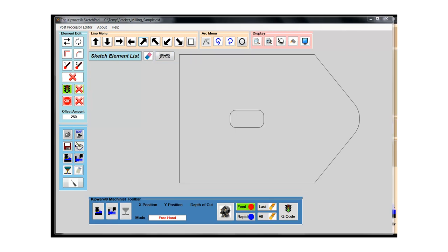So we're going to dive right into the drawing, and before I can do it, I need to do some calculations so that I can figure out a start point here where I can draw my tool path. Normally you could just use the elements that are here in the drawing from the DXF. But I want to show you how you would draw in the SketchPad. I want to show you a feature called AutoPath that's in the SketchPad that will automatically do calculations for you,